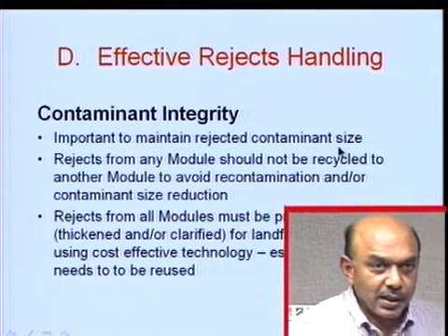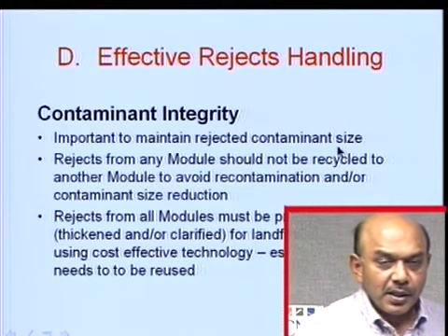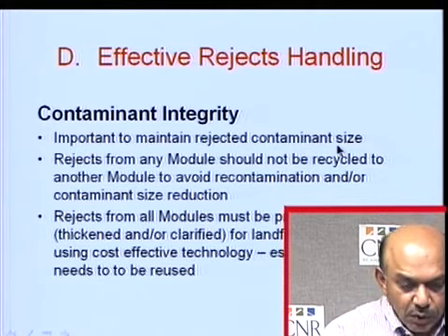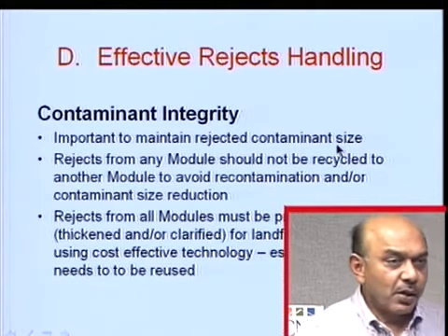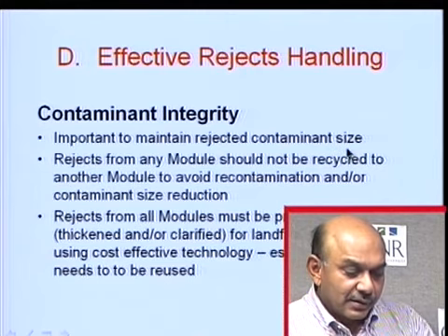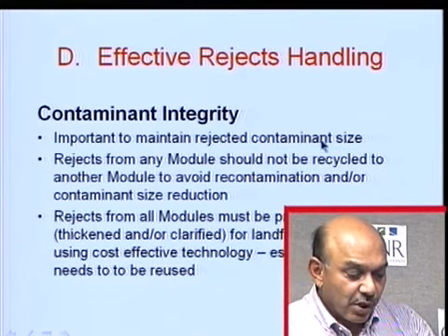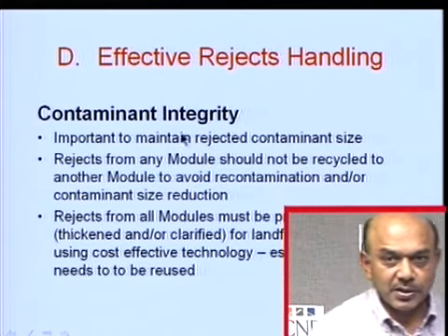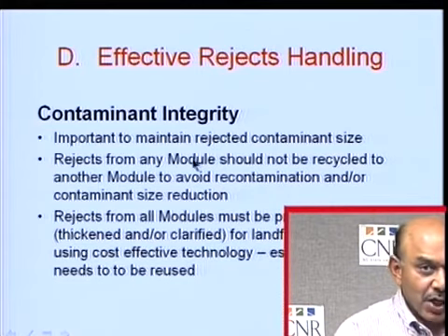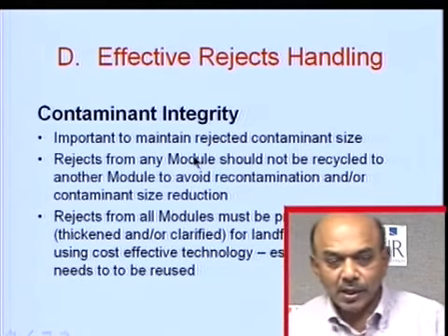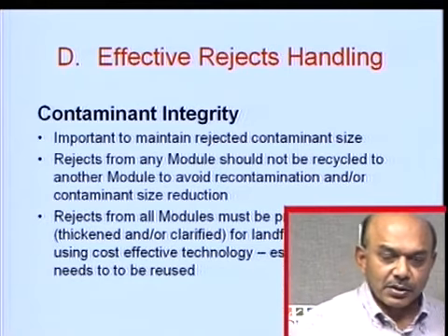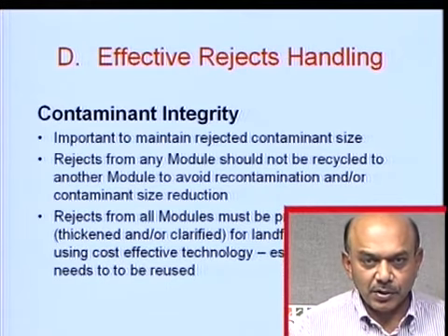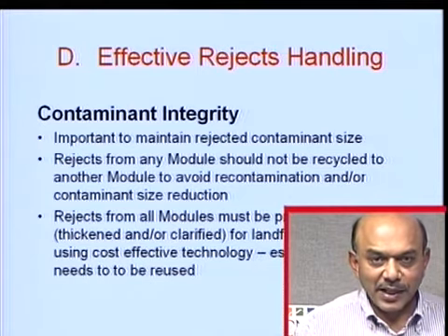If you let the contaminants be reduced in size, the chances are you will need more modules, or you will have a runaround and more system contamination, and the end product will have more contamination. You've seen that in the other example where we took the cleaner rejects back into the screens and we had problems. That's why early decontamination is very, very important, and it improves system efficiency. In a pulping module, the more contamination you can take out as early in the system and in the original sizes, the better off you are.